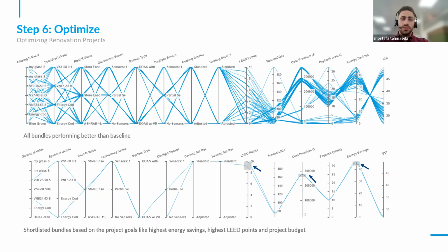In case you want to narrow down your search or you just, let's say, want to get 8 to 10 LEED points, you can use a bar here to narrow down your selection to the number of LEED points that you're expecting, or you can say, I want the EUI of 35 to 40, the maximum. If, let's say, I'm working on a government project that requires a specific performance, you can narrow down everything to the level required by your project and go from there.